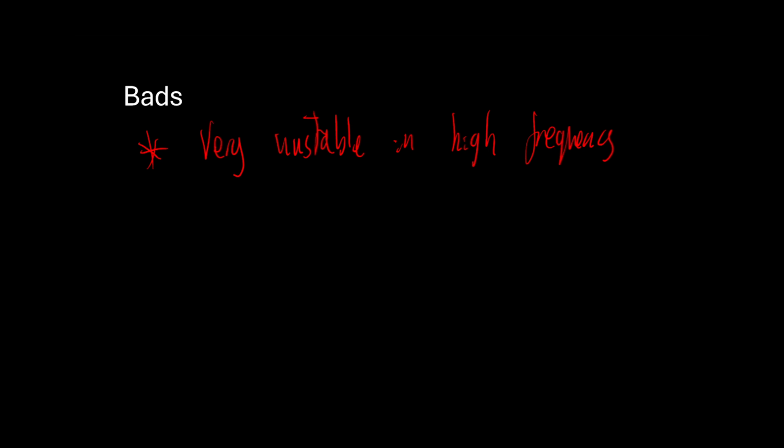Okay, so what are the bads about KD or differential control? It's very unstable in high frequency noise. Remember that KD is amplifying the rates of change of error.